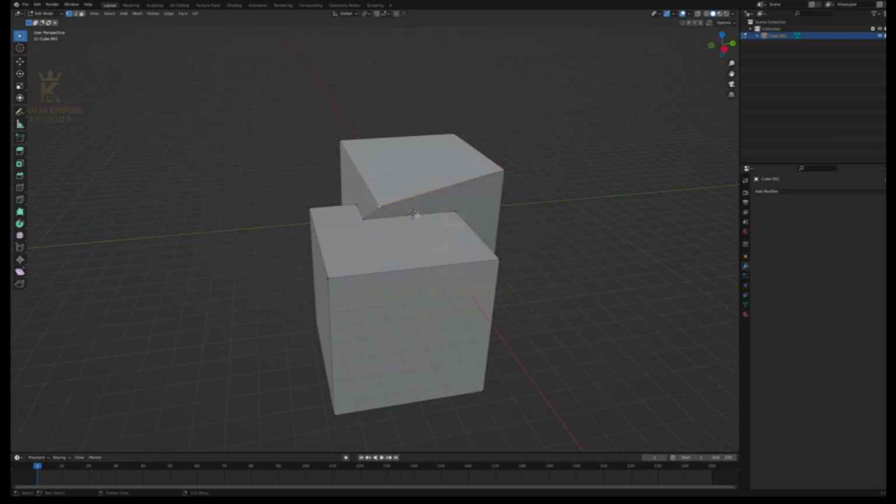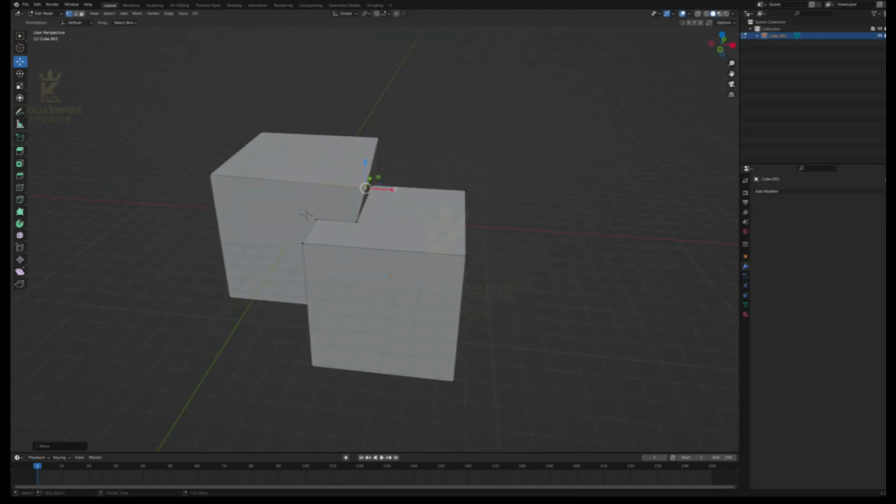So now our mesh looks like it's correct. I'll go ahead and move this. You can just go to the move tool. I used G for grab, the keyboard shortcut. It's to move. You'd think it'd be M, but it's not, it's G.